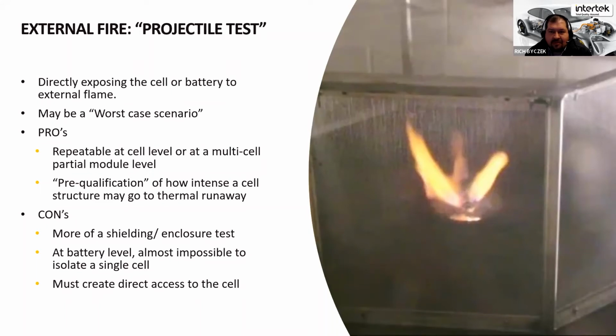Again, from a building code standpoint, we have the first concern that a battery could go into runaway, but we also cause a fire. But we have the secondary concern that if there was a fire from other combustible materials in the building that exposed the battery to that fire, similar to the electric vehicle concerns of a crash event exposing the battery, which is up until that point not experiencing a runaway, now it's going to see an external fire. Does that trigger the runaway? These are the concerns that we're trying to address here.